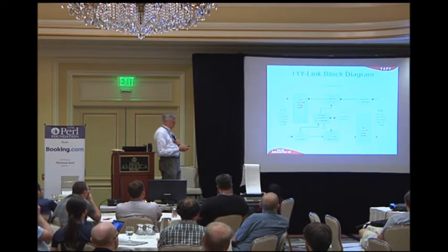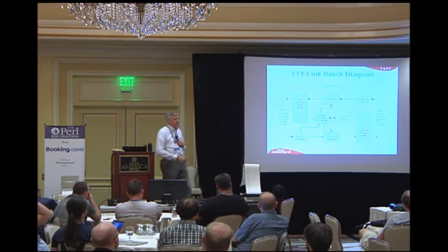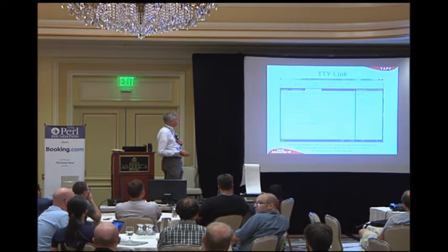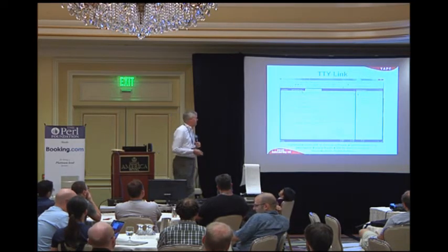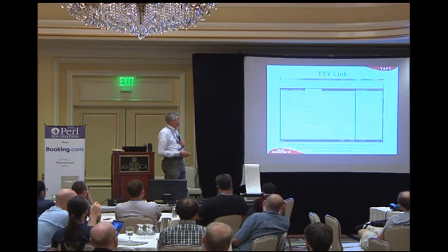Then I designed the functionality. A character comes in, goes into a translator, goes into a ring buffer, and goes out to the teletype. And we're coming back the same way. And then I had a few escape sequences with some shortcut memory, and I have a couple of local commands so I could get information on what's going on in this device. I first started out with Arduino, and it was really limited, so I switched over to Atmel Studio 6, a tremendous advancement over the Arduino. And it was all written in C++ and assembly using interrupt subroutines and so forth.